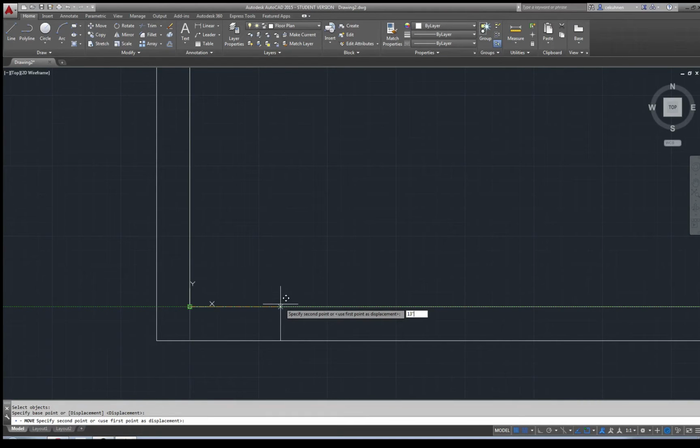And it's really important that I really move my mouse to the right really horizontally, and you see this dotted line. That means I'm moving it along a snap line, because if I click and I go to somewhere here, you see there's no dotted line. So I move it to the right and slightly down, but it should go straight to the right. Okay, 13 inches, enter, and there it is.